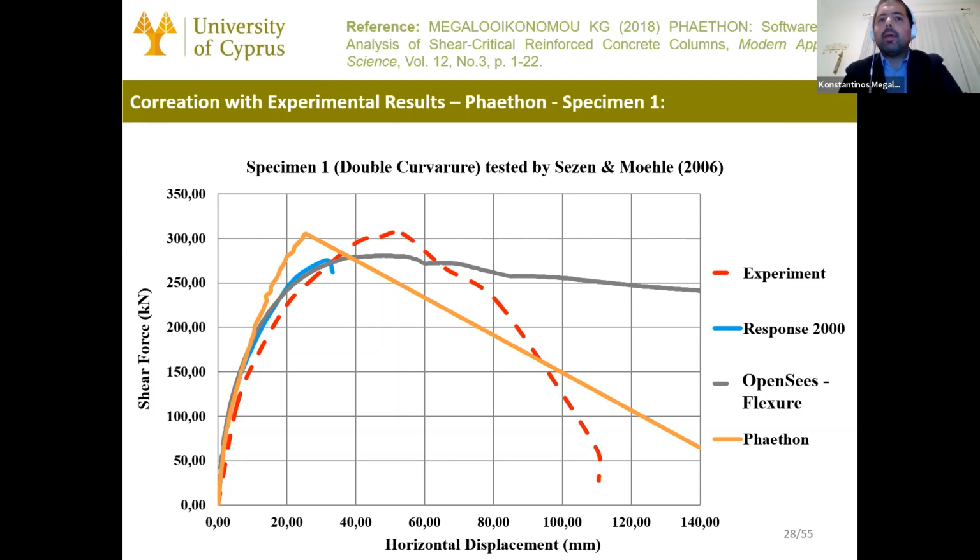So you can define the full response of a cantilever until shear failure. But even in Python, I couldn't capture the post-peak exactly. So I used one more point and a linear solution, because the way I calculate the capacity curve can capture only until shear failure. If you see the modified compression field theory and Response-2000, they give you the curves until the peak response.